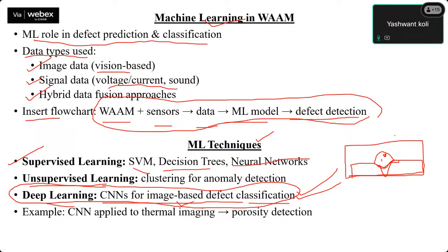So not only one defect is there, multiple defects can also be classified and we can sort them in a way like this is the first detrimental stage, second detrimental stage, like which defect has to be cleared first, what is the priority order of the defects. Suppose porosity is the major, important thing, so this is having highest priority, so we are giving 3 stars to this.